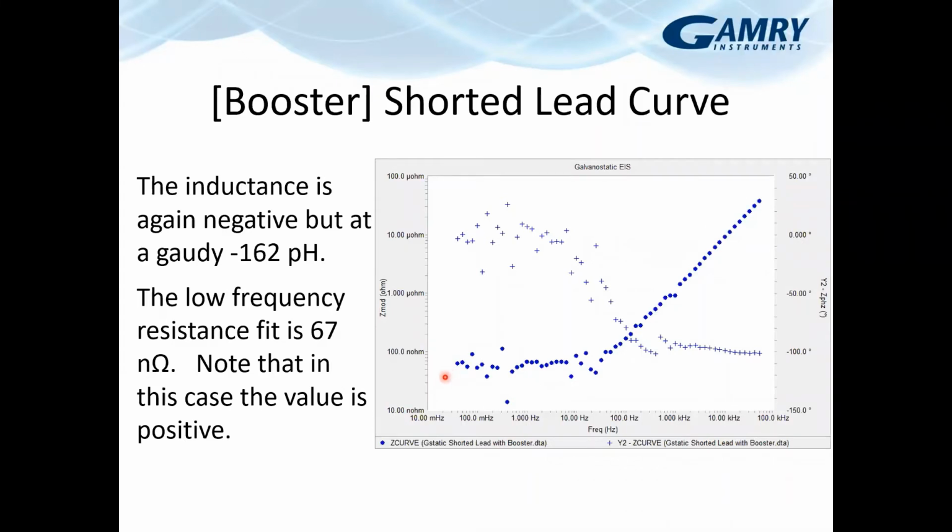When you're running your own shorted lead, you should note this shorted lead was set up such that there is zero contact resistance measured. That is, it's a 4-terminal measurement, but also both of the sense leads are tied to a single point, so there is no voltage drop across them due to current flow through a brass body that is being used for this.